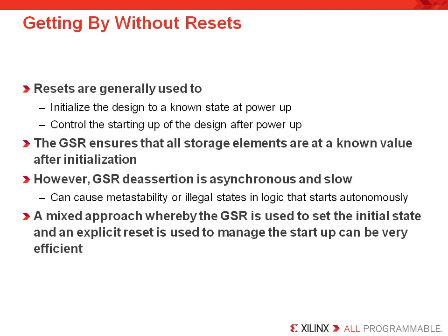That brings the next question. How do you get by without using resets? We mentioned that as an option. Now, resets are generally used to initialize the design to a known state at power-up. But keep in mind, in FPGAs, that's already done for you and available to you by default. You can't remove that. So the key thing to understand is you have to understand the initialization state and the use of the GSR when it's used by default as part of configuration.